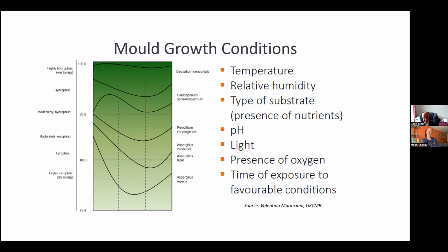And 9 times out of 10, you'll find that it's not the presence of hygroscopic salts. It's actually the fact the wall has got too much pressure, because the soft landscaping is up against the outside of the building. The water pressure, when it rains, it stores the water at the base of the wall. The wall acts like a sponge, pulls it up. Take the pressure away, put a drainage channel on the outside of the building.